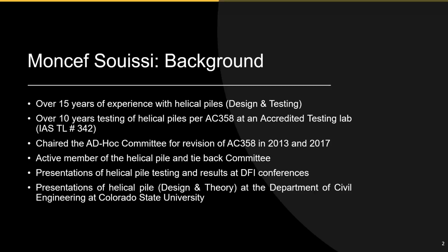AC58, AC stands for acceptance criteria. So whenever you have a new product and you want to have an ICC-ES report, if there is no criteria about that product, you have to work with ICC-ES to create an acceptance criteria. Okay, so that's what happened with the helical pile manufacturers. AC stands for acceptance criteria.